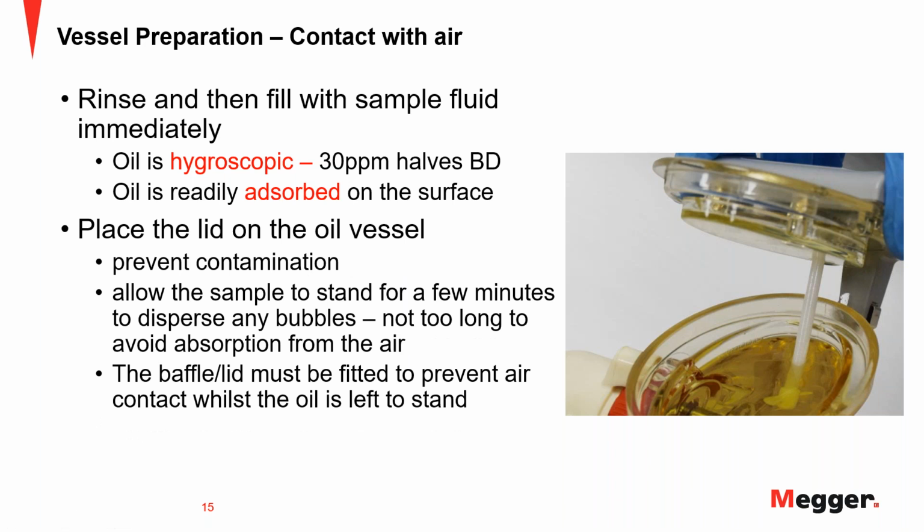Okay, and then the next thing we need to do is place the lid on the oil vessel, again, to prevent any further contamination. We also need to make sure that we allow the sample to stand for a few minutes. This is to disperse any bubbles that may have been created by pouring the oil into the test vessel. But we also need to make sure that we don't do this for too long, because it can also cause problems with the hygroscopic properties of oil, because it's always trying to absorb moisture from the air. And then the baffle plate and the lid must be fitted to prevent air contact while the oil is left to stand, as you can see there in the picture on your right, the baffle plate in place with the impeller below.